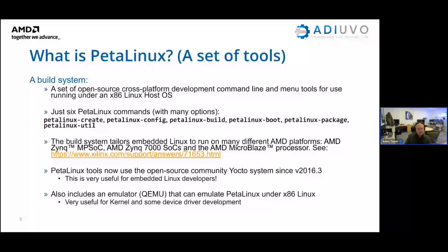then. So one of the nice things about Petalinux, obviously, is that it basically uses Yocto, and it wraps around the 2016.3 version. It wraps around Yocto and gives us a nice build system around that. And if we want, we can even emulate it using QEMU on our processor. So it works really well.